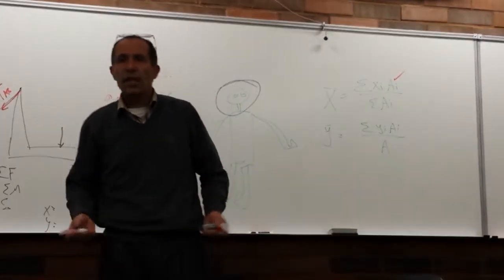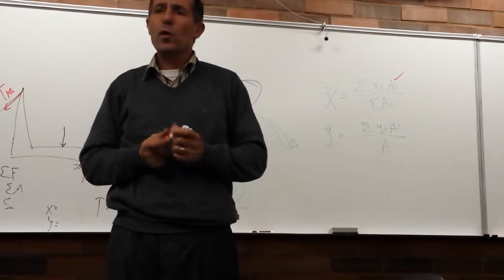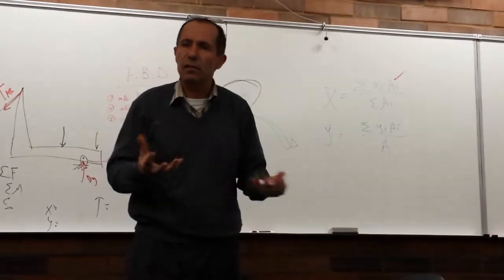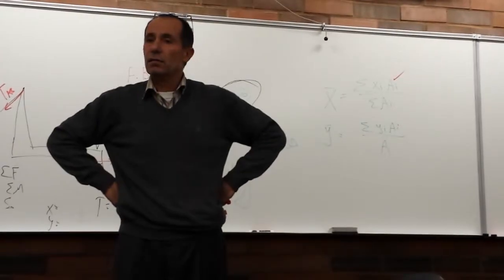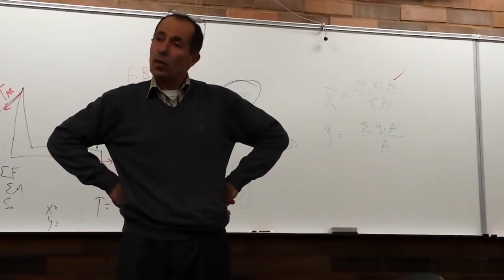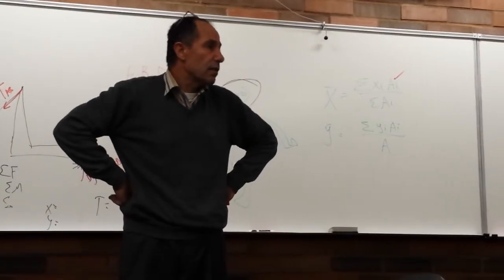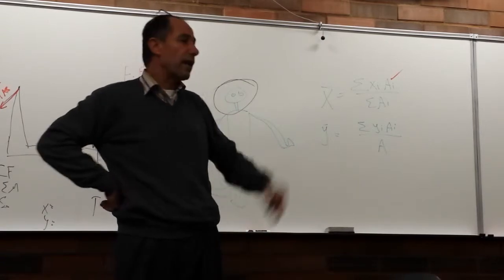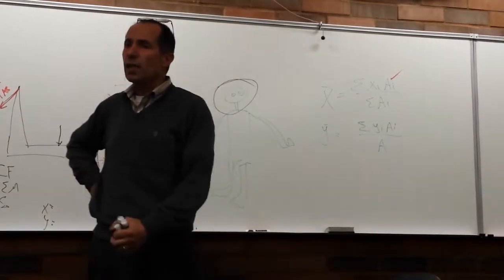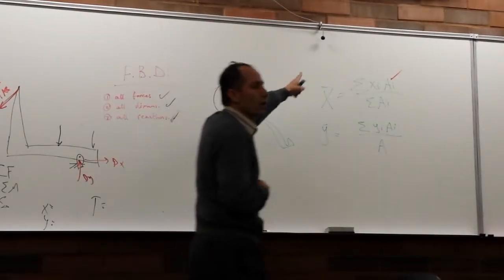After that, if we don't learn about anything else, and tomorrow you are an engineer and you need to think about, I need to find center of gravity. I can calculate the area. Area times height is the volume. Agree? So makes your life easy. Volume times density is the mass. If I need to go to the weight, times the G. Done. So that's why we focus on the area.